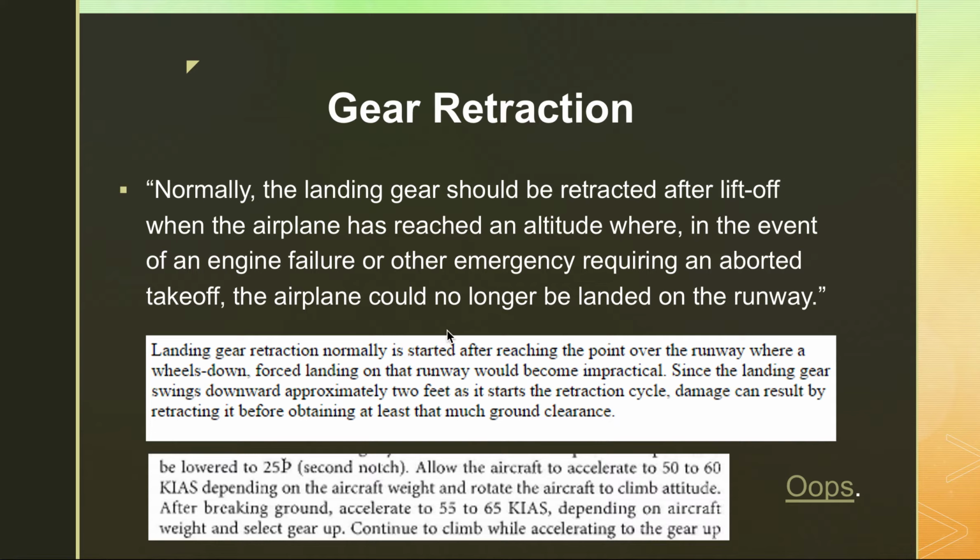And then I cut and paste from a few other POHs that talk about that. Now, the 172, the Cessna single engine series of retractable gear, the landing gear goes down as it retracts, about 2 feet worth. So make sure that you're at least 2 feet in the air before you retract the landing gear. And then just different aircraft are different. And then don't pull it up too soon.